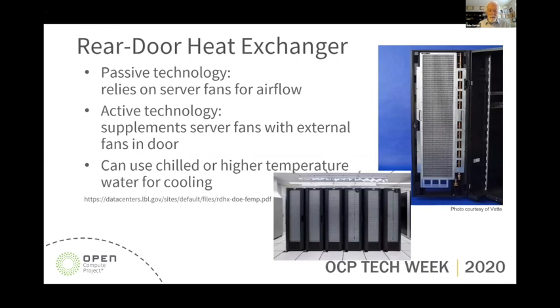The next technology would be the rear door heat exchangers. There's passive technology, which relies on the server fans for airflow. And then there's active technology that supplements the server fans with external fans in the door. These systems or rear doors can use chilled or higher temperature water for cooling.